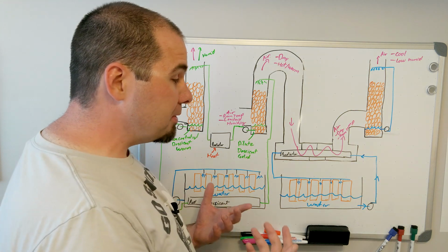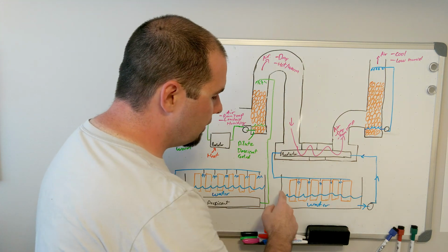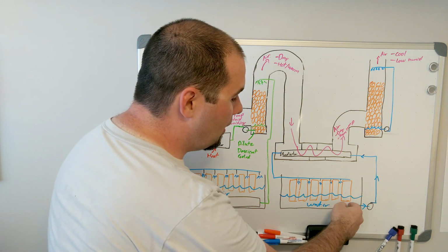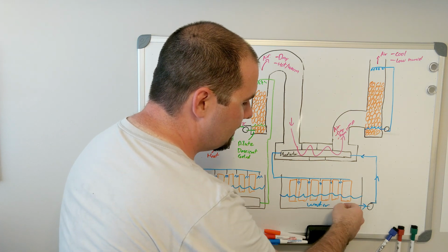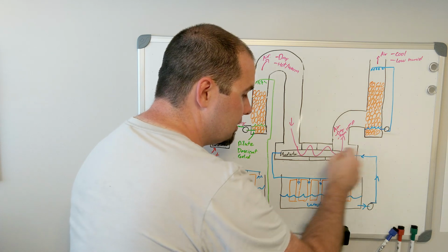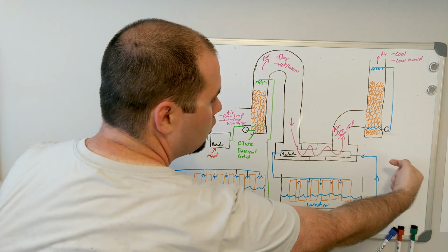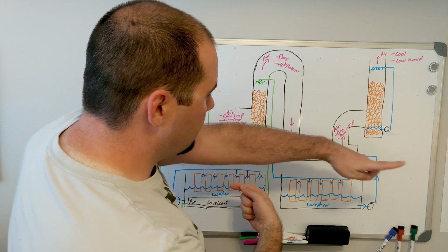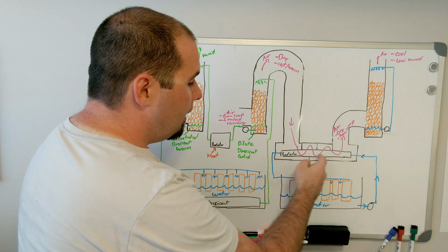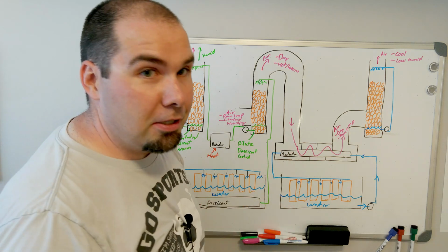And how he's accomplishing that is he's taking his radiator and he's running it through another swamp cooler. So the water is exiting through the pump. This water will be cooled, as he demonstrated with his column system, runs through the radiator. It's counterflow, so cold going this way, hot air going this way, so that there's the largest temperature differential between it. Or I should say, for the longest time.